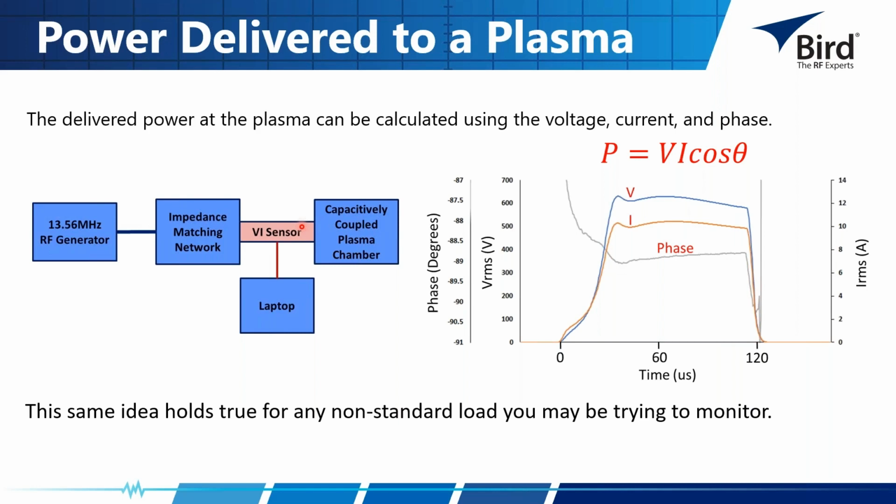Then we're taking into account any small phase variations or mismatch that could be due to the connections on the cable, or performance pieces with the sensor. We have that all lumped into one calibration table now, and it allows us to effectively cut the uncertainty of what would be the standalone components in half. So we do see people use that quite often to squeeze a little bit extra accuracy out of their unit.